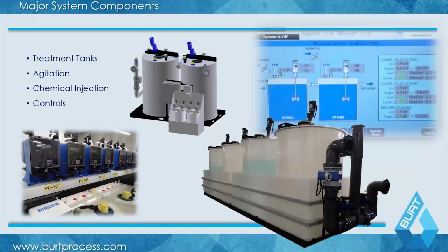And each of these stages is based on the industry standard residency time of about 20 to 30 minutes, depending upon the relative strength of your waste. And this is achieved by what's referred to as creating a CSTR, or continuously stirred tank reactor, as part of your treatment system, as well as the agitation that goes along with it. And here are your agitators, which are located here.